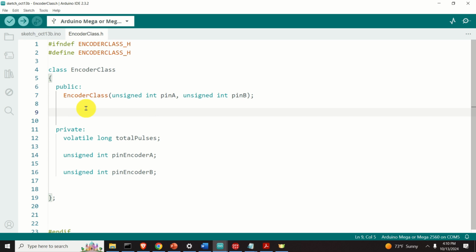In this video tutorial, I will teach you how to detect pulses with high resolution and with low resolution. I'm doing this since low resolution is beneficial when your shaft is spinning relatively fast and when you don't care about the actual resolution, although the low resolution is probably still enough for most applications. On the other hand, I will also teach you how to measure the pulses with high resolution. However, high resolution is not suitable if your shaft is spinning very fast, since it's going to use more interrupt time and more digital read time.